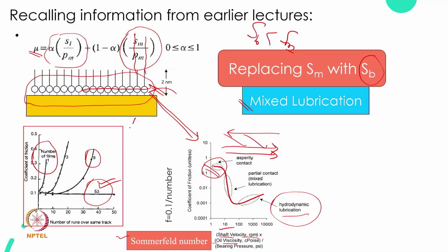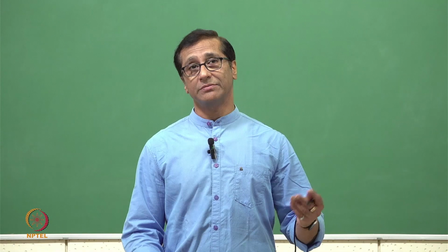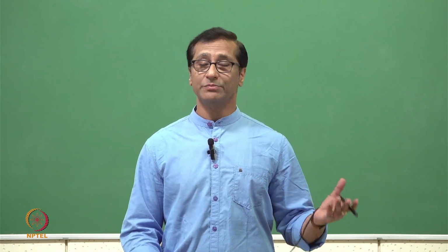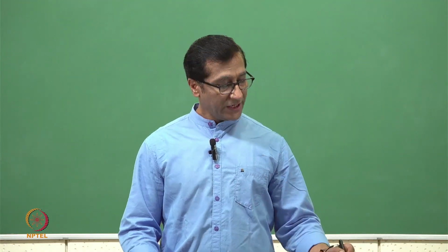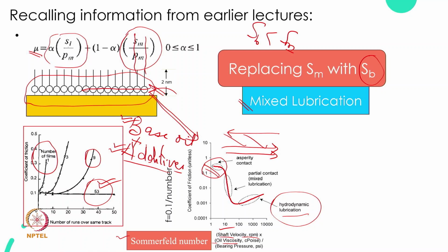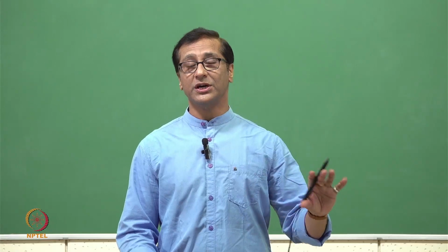So in short, we can say there will always be a base oil used for the lubricant purpose plus an additive package. If we don't have the additive package, we may have more wear, maybe more friction at the beginning and the ending. Just to avoid that, at least we require this one. And of course, if the temperature is on the higher side, again the base oil may get thinner, or we say that viscosity will be lost. Again, we may require some sort of additive. That's why we use the term viscosity index improver. That is really required. So in reality, a lubricant has to be always something like a base oil plus additives, if we are talking about the liquid lubricant.